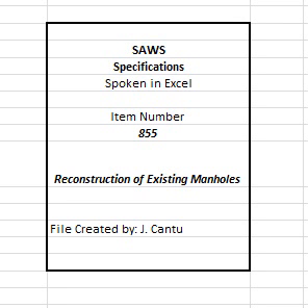3. All excess materials, of any type, shall be disposed of by the contractor at his own expense, and in an approved location. 4. Reconstructed manholes shall also be cleaned of any debris as required by the inspector. 5. If a new manhole cover, ring, or reconstructed manhole is damaged by the contractor, it shall be replaced, as directed by inspector, by the contractor at his own expense. 6. All installed throat rings must be used in conjunction with a UV-stabilized polyethylene liner and I/I barrier.